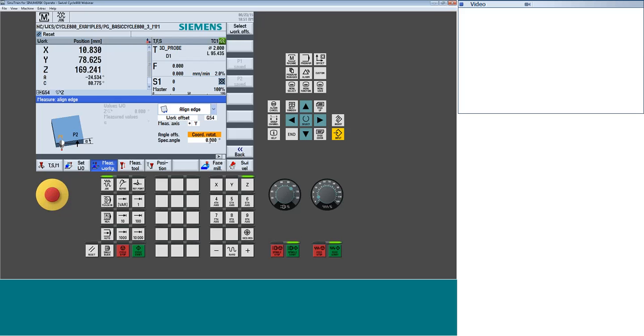So in a scenario like this, if I know that my program coming in is direct axis positioning, where it's calling out for C's and A's and all that, then I'm probably more inclined to set up the machine to match that. So set that up with a direct rotary axis value. But in this case, we're doing everything around coordinate rotations. So you come in, I now probe 2 points, so I can cycle start, machine comes over, feeds, touches. Now, in this case, I'm going to follow my picture. So I'm going to move over. Maybe I know it moves up just a little bit. I cycle start.